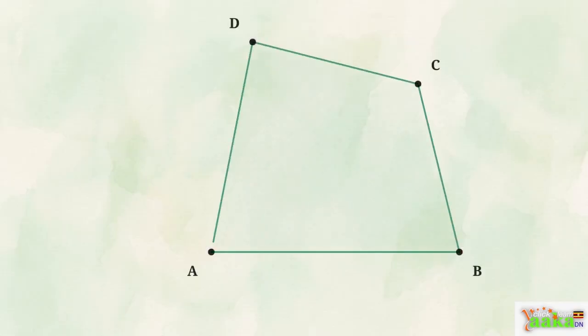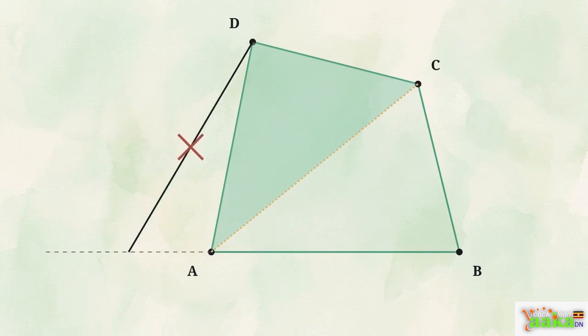We'll start with the original four-sided plot on the drafting table. Our first goal is to reduce these four sides down to 3. First, we draw a diagonal line connecting point A to point C. This isolates one corner, creating a temporary working triangle. If you try to guess the next line by eye, your area calculation will be inaccurate.